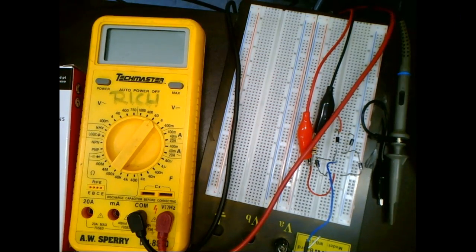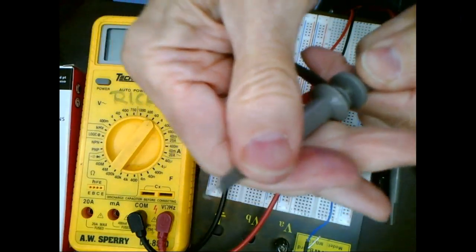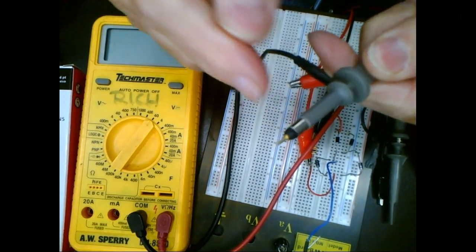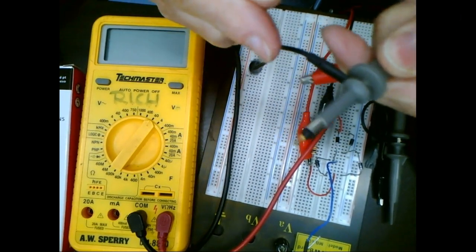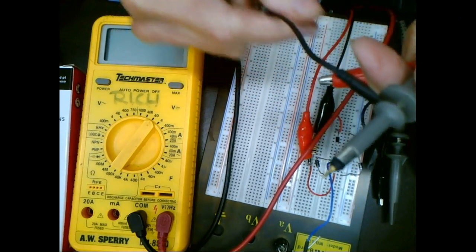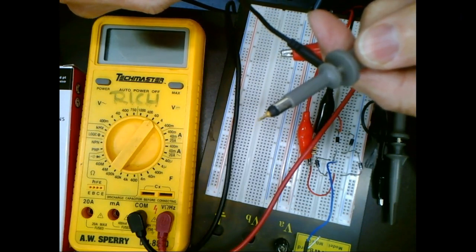This scope probe here, to prevent it from acting like a capacitor, they bring the ground lead all the way down to here. So the ground is brought all the way to the tip. So guys, if you pull that thing off and you say, well, I'm going to use that, you've got to remember your ground is sitting right there. I've seen people blow scope probes up just by accidentally touching this in the circuit, and they got their ground reference over there on ground, right?